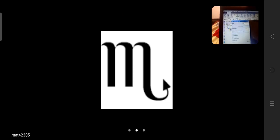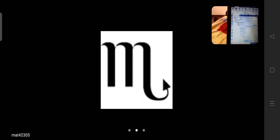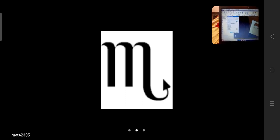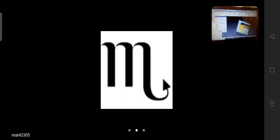Okay, this is because of NX 11. I click there, that is fine. I'll show you how we can do that. Click on specify part boundaries. No need to change anything there. Just click on the faces of that body. Can you show me the other side? Yes. So select the second face. Yeah, that one. And click on your middle mouse button.